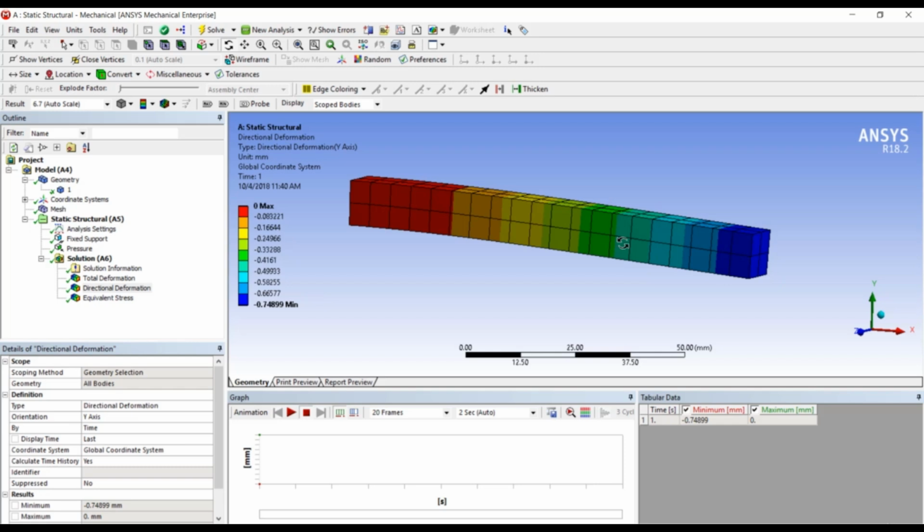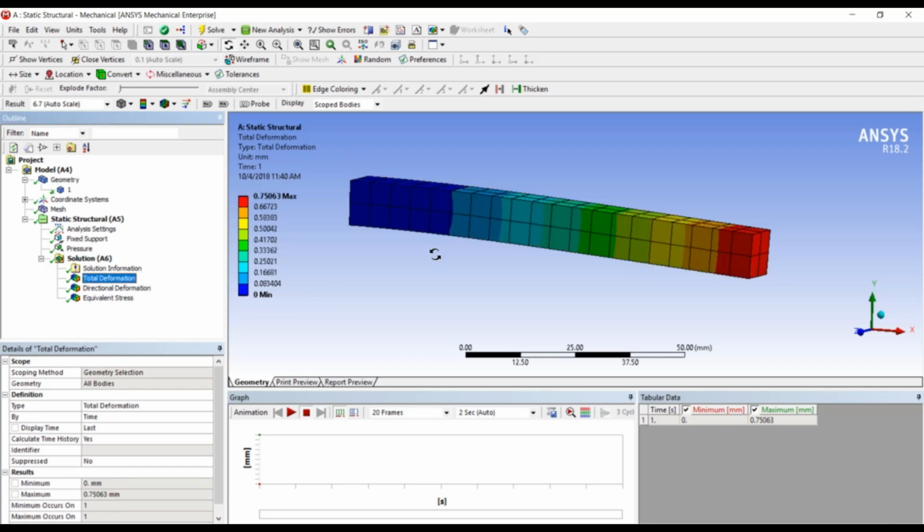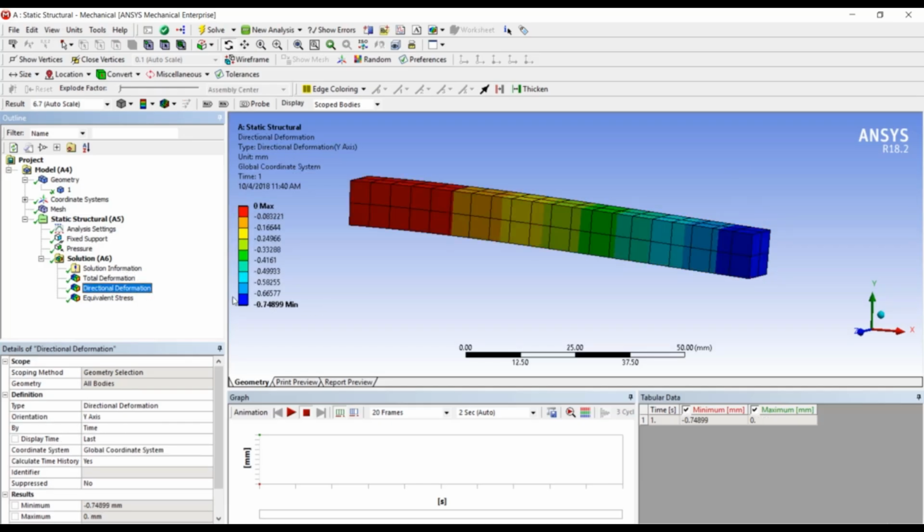And coming to the contours, in the total deflection, the highest deflection was represented by red. But here also the highest amount of deflection according to the software is 0, because if we take negatives, 0 is the highest number. That is why it is representing the highest value here and the lowest value in blue color here. So as a CAE engineer, you should not go away with seeing different colors, and you should not be saying whether the component has failed or not based on the colors. You should be able to understand and interpret these particular results.